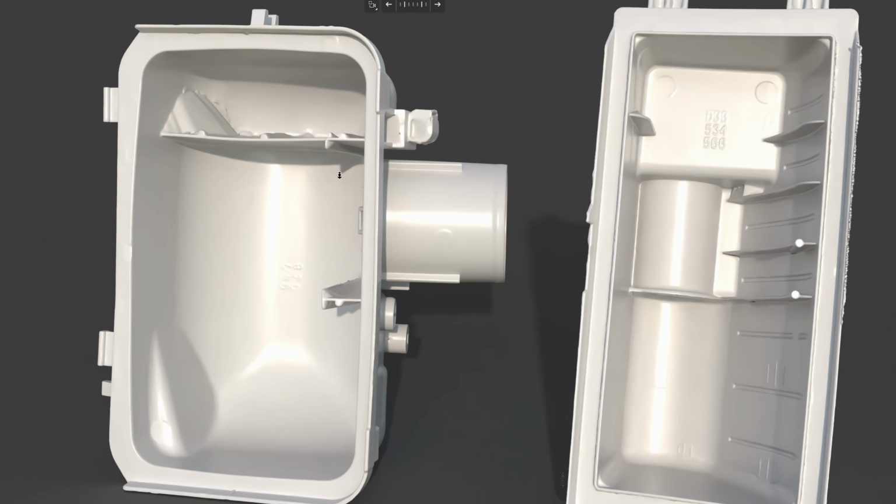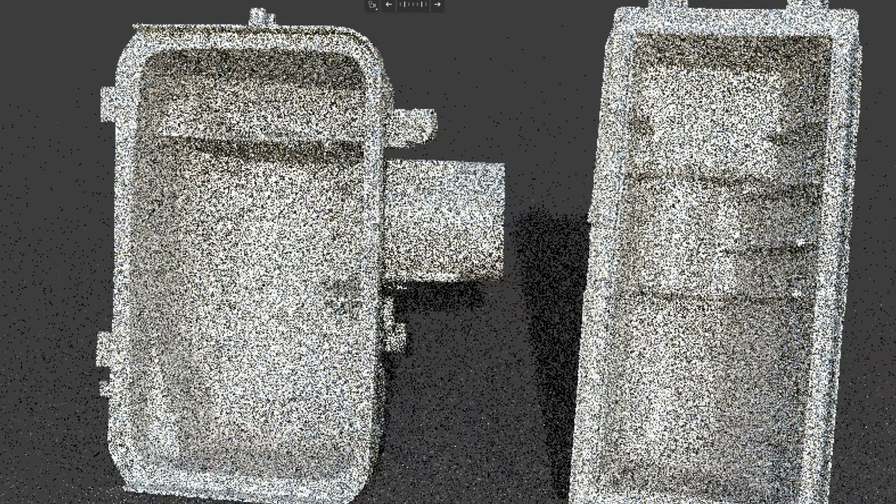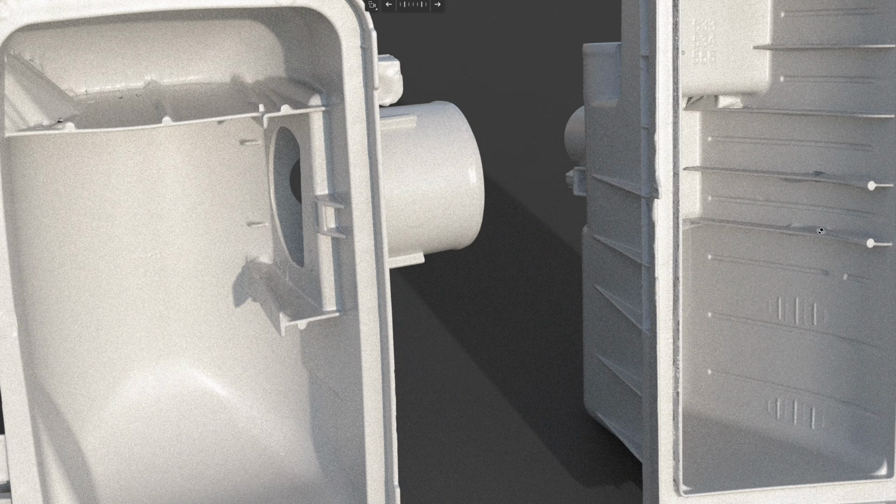You are going to see a blind spot from the 3D scanner because the object is blocking itself from the 3D scanner. So those blind spots have no surface data. So when you mesh the 3D scan, the software will try to fill the holes using random surfaces, like in this part and in this part, as you can see here. Let me move this a bit, like this part and also this part.